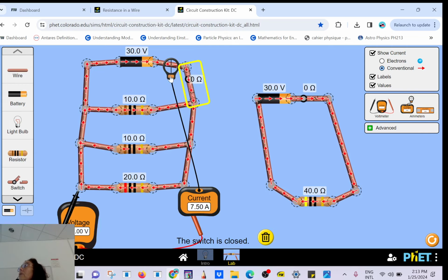So it's like if in your house, you play the music and you turn on the microwave and you dry your hair, all those machines can work at the same time, but of course you are draining more current, so you are spending more money. I mean, you are draining more energy. Except that sometimes you have a fuse because you don't want to go over 20 amps. So if you keep turning on loads all at the same time, at some point you're going to reach the maximum 15 amps or 20 amps. So of course you have a safety fuse that will break the circuit. Okay? This is how it works.